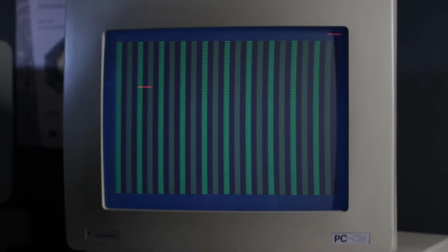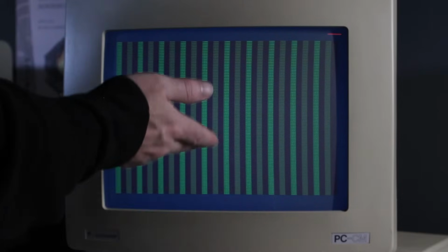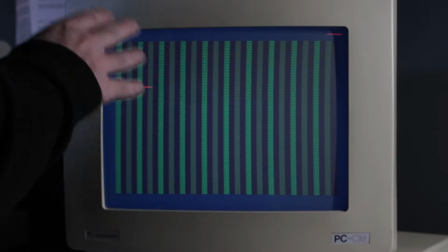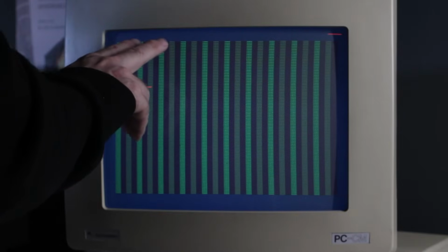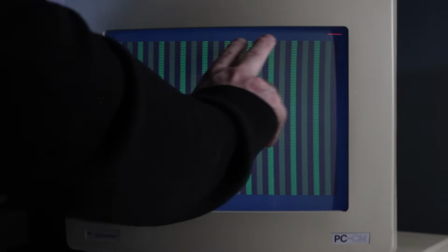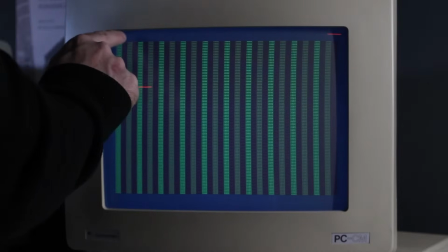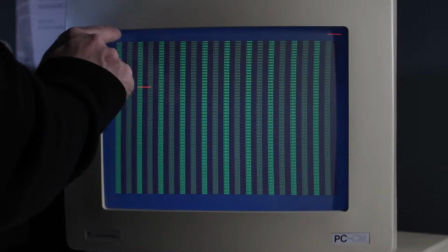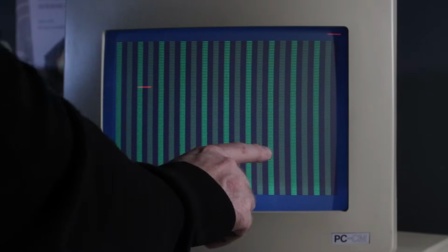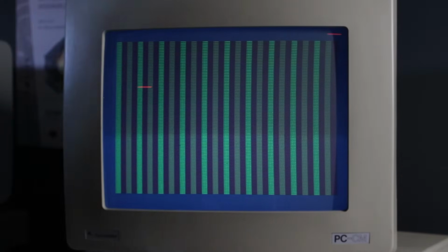So what I want to figure out is where are the no-go zones, maybe where the graphics chip is reading the graphics RAM itself, for example, and it can't allow the CPU to access it at the same time. If I can figure out exactly where those no-go zones are, then it'll be completely safe to do accesses to video RAM in all the other locations, and we should be able to get an optimal schedule for accessing video RAM for pixel information.